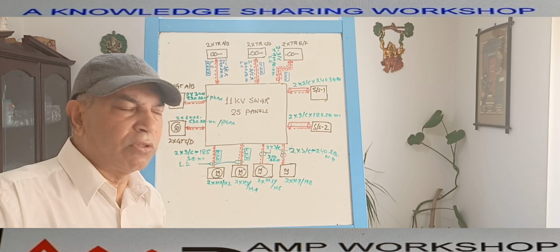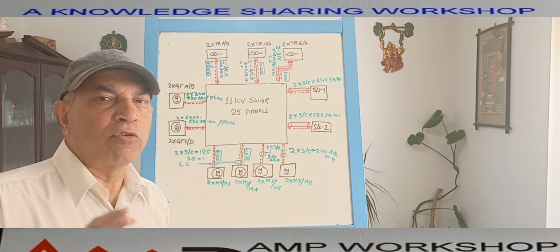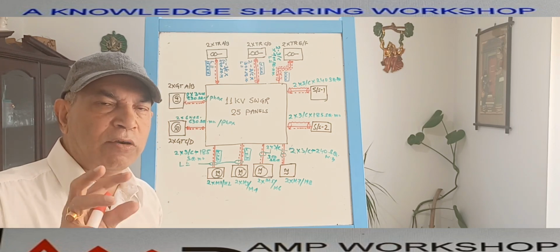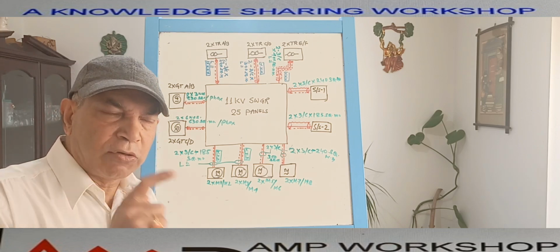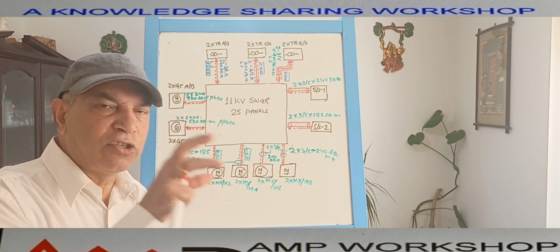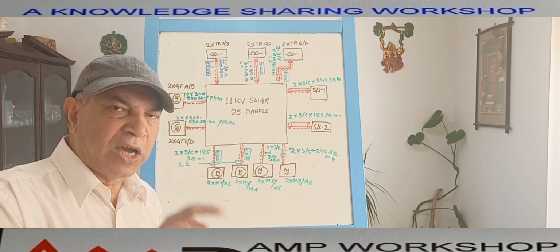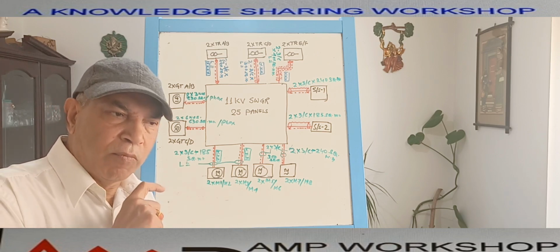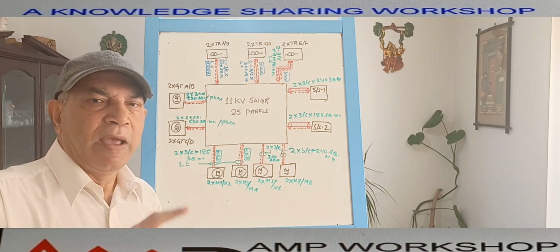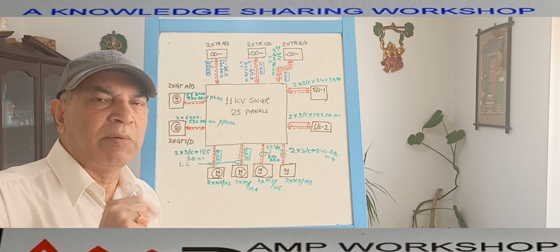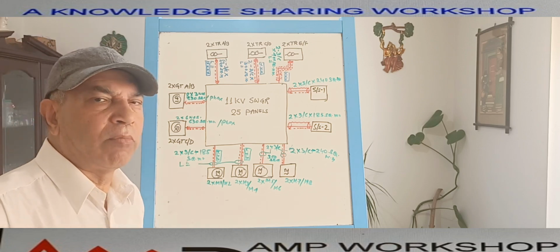If you look into the FEED document or the conceptual design document, you can see there is an overall layout of the plant. In that plant, all the field equipment and major equipment are shown at tentative locations. Then, based on the tentative location, the size of each equipment is also decided in the FEED document or the conceptual design document. From the size of the equipment and the length, most companies in the conceptual stage calculate the cable size, and from that there is a document, the cable size calculations. This document is important to develop the cable block diagram.